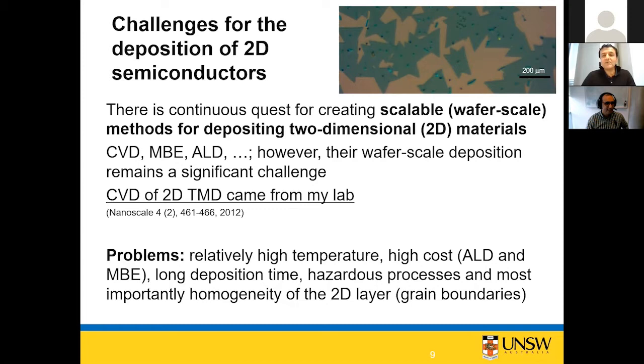They don't grow on top of each other, but they really do grow on top of each other most of the time. The growth rate is very small. If you use other methods, as you see, it doesn't even cover the surface fully. You use other methods that cover the surface, and it's two-dimensional, like MBE, molecular beam epitaxy, it is very expensive. You need super high vacuum. All these problems, they haven't been commercialized yet. I mean, the wafer scale solution, not the reactors.